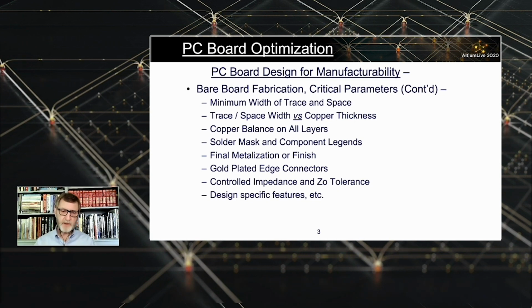Design specific features, there are a lot of, controlled impedance. Do you need controlled impedance? You're going to pay more for that. What tolerance do you need? We'll talk about that in 1 second.